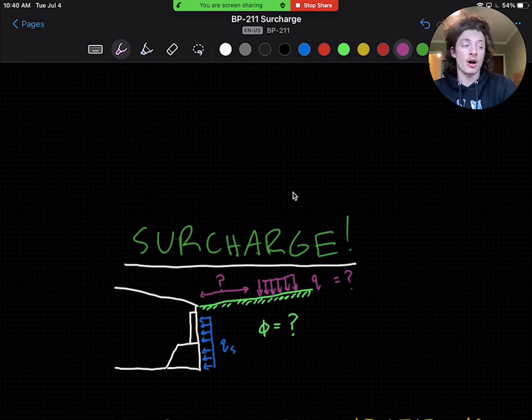Lateral earth pressure is already a result of the self-weight of the soil squishing soil beneath it and causing lateral pressure. The coefficient K, explained in the previous lecture, is essential in how we translate this vertical pressure to a lateral pressure. K is specific to the properties of that soil backfill layer, so any extra weight beyond the self-weight of the soil is considered a surcharge and is translated from vertical to horizontal pressure using the K of the soil layer contacting the wall.